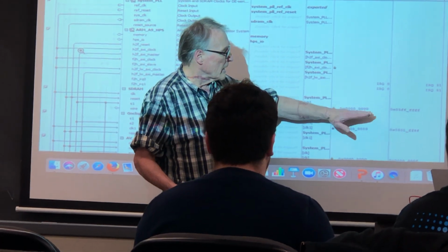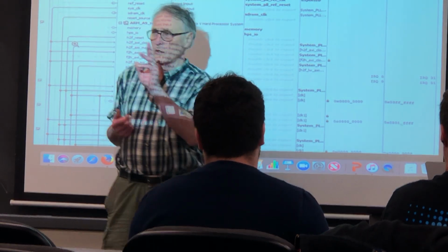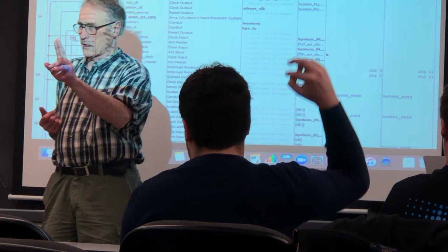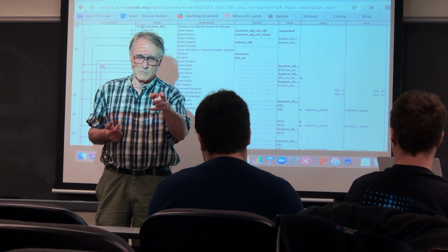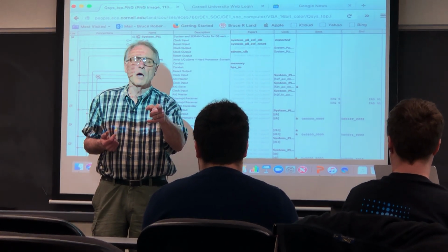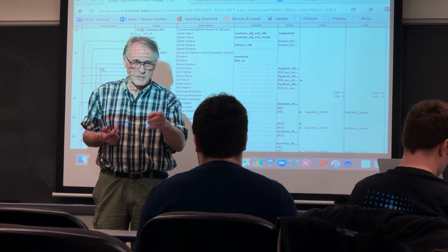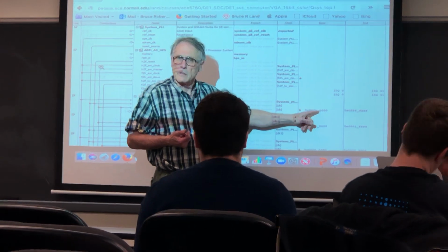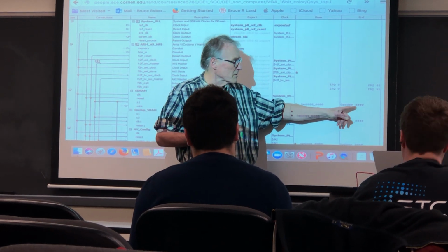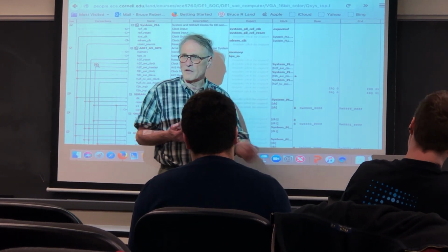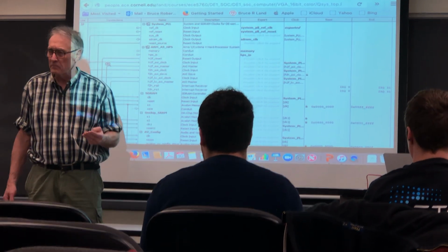So this is an address which is local and in the range onto the FPGA, and it must be unique. There can be no overlap in that range. How much of this layout is stuff that was just set up for the system in general, or is stuff that you set up yourself? C00 is hardware, real hardware. You don't mess with that. You cannot mess with this. These addresses you can change any way you feel like, as long as the span is hexadecimal 400000, because that's the physical size of the actual SDRAM, which is 64 megabytes.